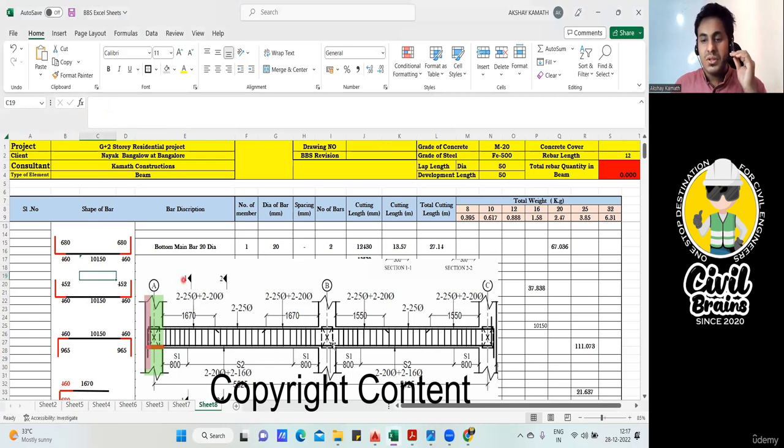On the left side I did the same thing, and I should do the same on the right side also. So again, this is your column, and this red color bar is not going completely outside. It will stop up to here. That means we have to leave a cover, a 40 mm cover on the side. Then what will be this red color distance? What is the size of your column? It is 500. So 500 minus 40, here also it will be 460.